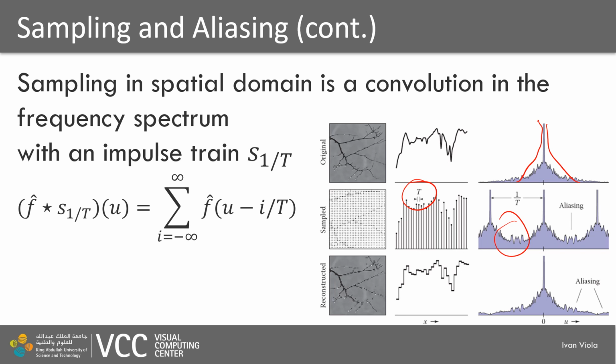You can see that we have been using the multiplication with the sinc filter here, and you can see that this frequency is coming from the second aliasing spectrum in the negative direction, and this part is the aliasing from the positive copy of our frequency response.